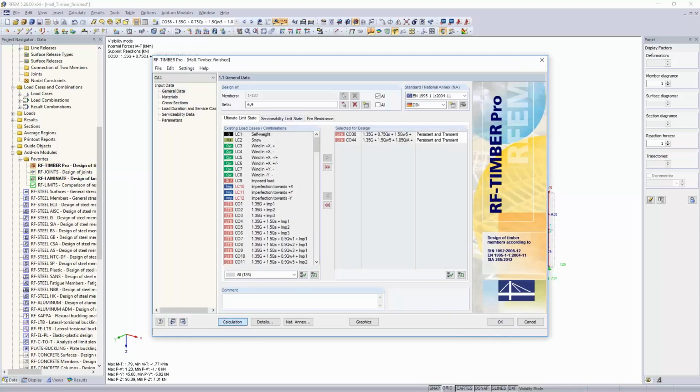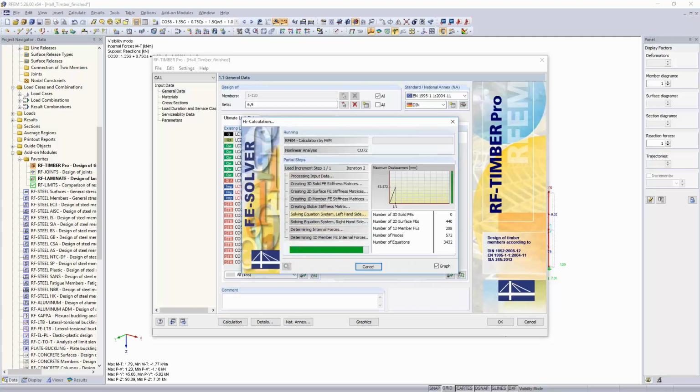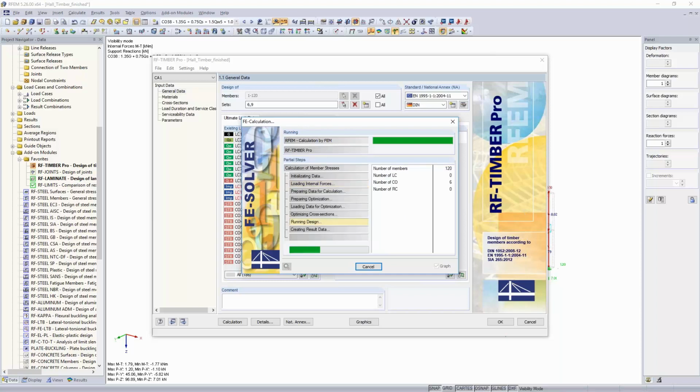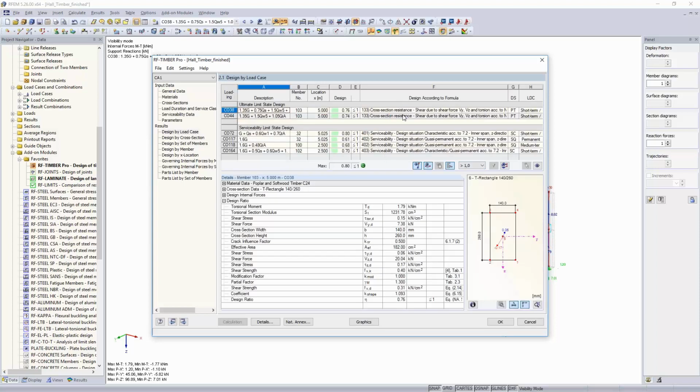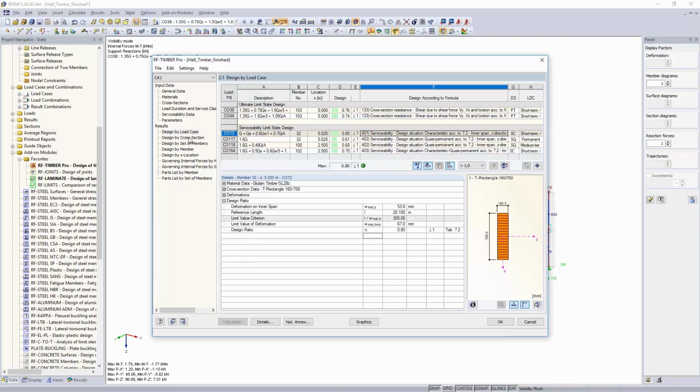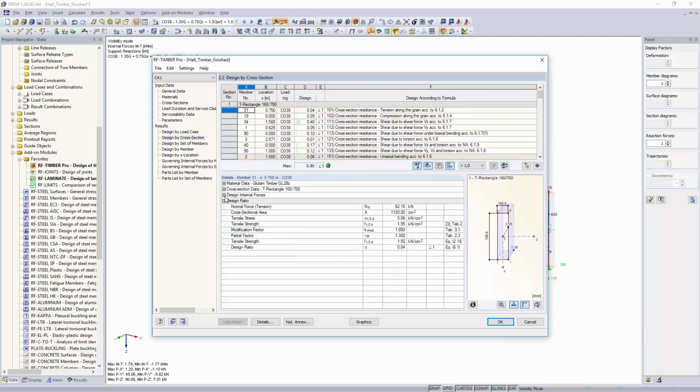we keep the serviceability limit state. It maybe makes not so much sense here, as we saw that the serviceability limit state was not really a problem, but maybe we want to see the deformation in the longer set of member. There, I want to show you also the graphical presentation of that. And now you see we do not have any problem from the ultimate limit state, and design governing is now serviceability. All verifications are listed here, and you can recalculate everything that's done by the add-on.